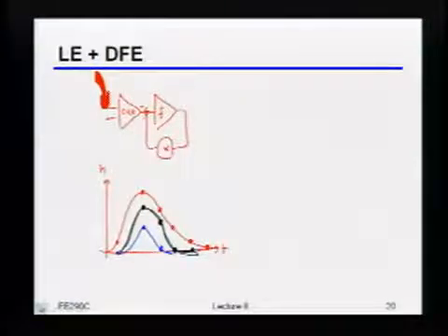It doesn't really matter because even if it's a parallel link or something like that, the data is independent, right? So it may indeed fall on the cursor, right? But the trick is that crosstalk usually is at a fairly high frequency, right? Because it's usually capacitively or inductively coupled, right? So just by me being able to back off on the bandwidth of the CTLE, I'll be filtering the crosstalk more heavily, right? It's not that it's going to go away, but at least I won't be amplifying it as much as I was in the past.